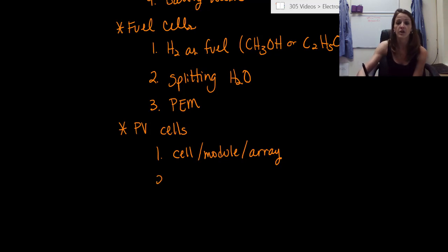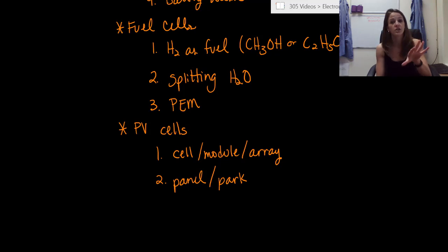We also talked about how we can use photovoltaic cells just in a panel, a single panel like we saw with those gentlemen who were able to pump their water using a solar panel, but we also saw what's called a solar park. And so we know what a solar park looks like. We know the direction of the solar panels: in the northern hemisphere, our solar panels have to face the south. In the southern hemisphere, our solar panels have to face the north. If they don't, we're not optimizing our incident radiation. It's just a waste of everyone's time and money.